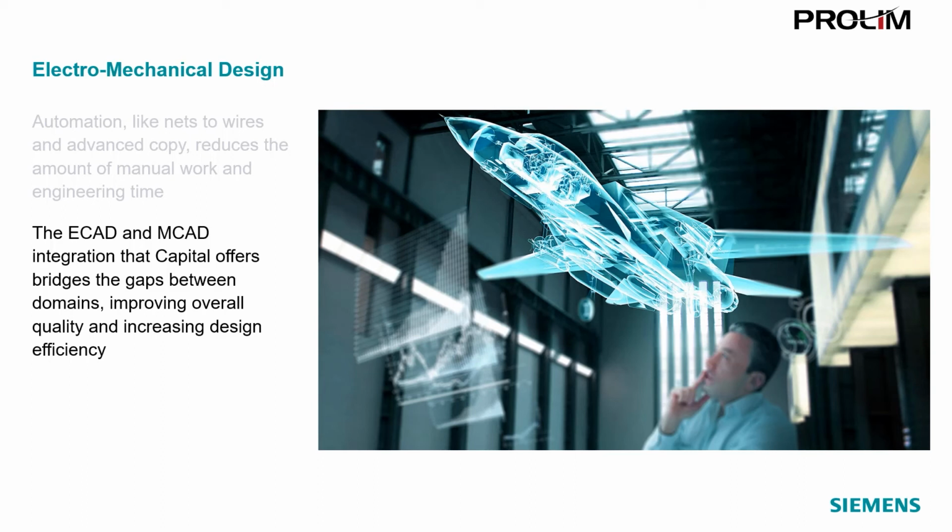So it's improving overall first-time quality, reducing your program risk, and also increasing design efficiency by allowing automation, with things like that routing assistant, to easily identify where those paths need to be taken, placing those inlines, and also back annotating that information directly from that MCAD data into your physical wiring designs before we push that off even into the harness.